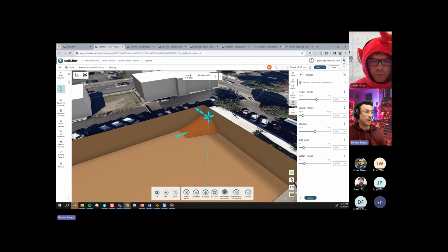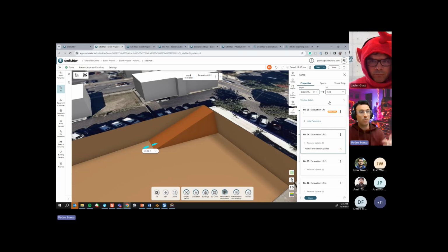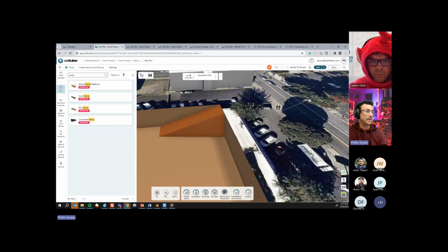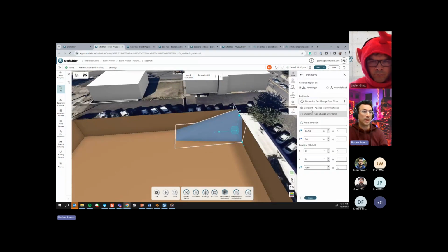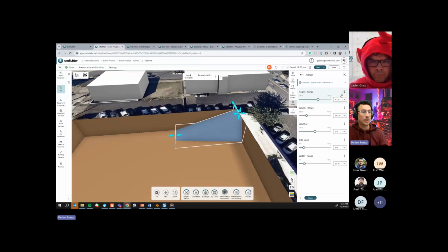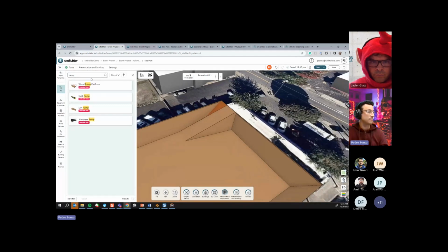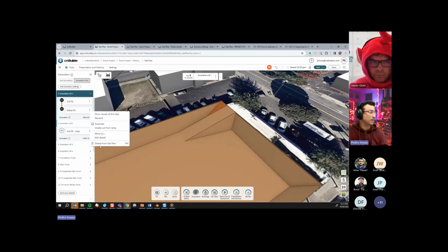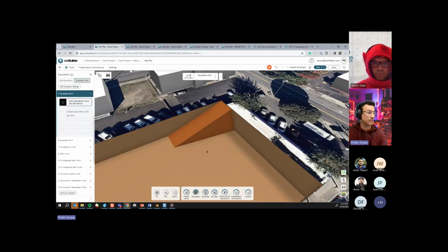So I could simply go in here and adjust this ramp based on the geometry of my cut, and then I will make this ramp show up on the first milestone, and I will remove this ramp on the last milestone of my excavation, for example, right? So if I do that, now I have a ramp going on over here. Oops, let me just make this ramp position constant, and also all of these are constant, right? So now if I go back, I can completely delete the first ramp that I created, and this one is going to stay there throughout my whole excavation steps.